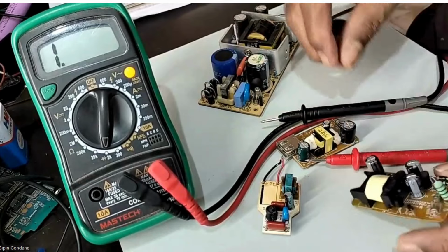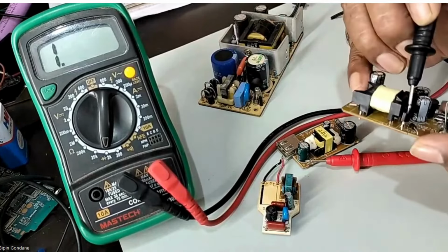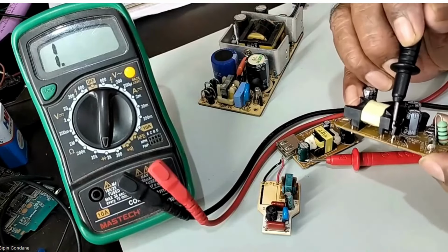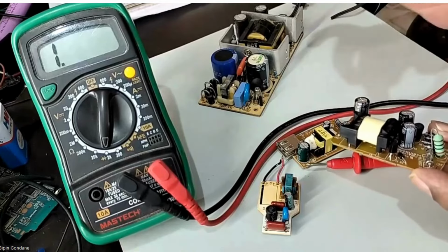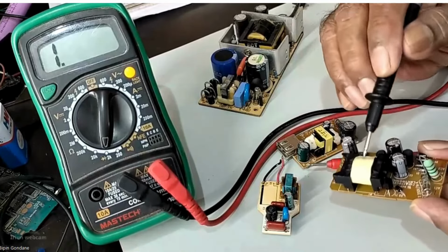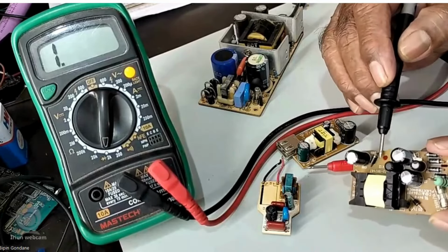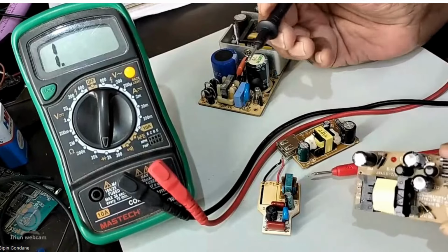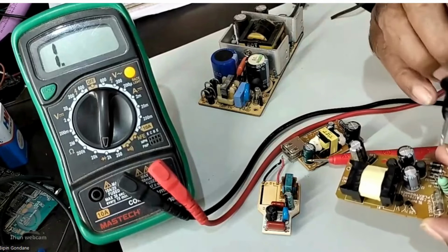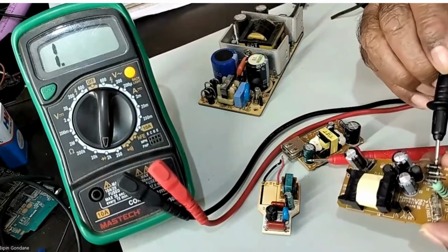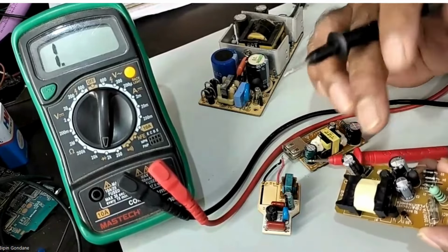Now the fourth important point we have to check is this transistor. It can be a transistor, a MOSFET, or an IGBT. We have already discussed in previous classes how to check it. The transformer usually doesn't fail. On the secondary side, you can check this diode and this capacitor, but usually the problem doesn't come on the secondary side. The maximum problems, if you are familiar with how to check the diode, resistor, fuse and transistor, 90% of the problems will be on this side.